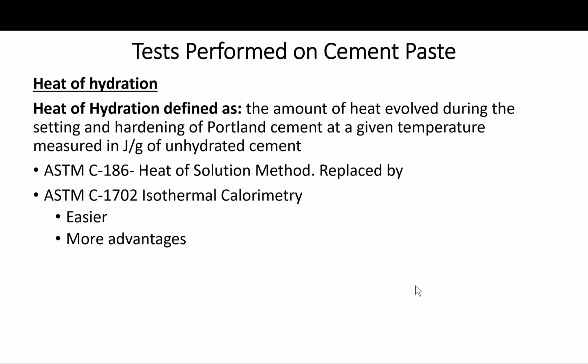Okay, next test we have the heat of hydration. As you recall, we stated that the cement hydration is exothermic, and the rate of heat evolution and the total amount of heat are of importance, especially in certain conditions such as when we are pouring mass concrete sections.